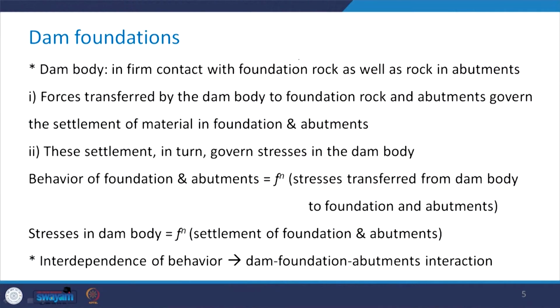Now this dam body I showed you is in firm contact with the foundation rock as well as the rock which is there in the abutments. The forces which are transferred by the dam body to the foundation rock and the abutments govern the settlement of material which is there in the foundation and the abutments. Now what happens? These settlements in turn govern the stresses in the dam body.